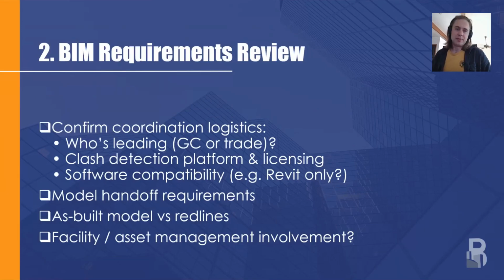So, BIM requirements review. This is getting back to the BIM execution plan. Some items to review within this: who's leading the BIM coordination process? Some general contractors run it internally or outsource it. Either way, I would consider that a GC-led process, or some general contractors outsource it to trade partners. So a lot of times this ends up in the mechanical contractor's court because they're taking the most space.